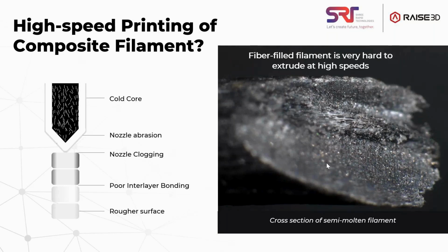So the question I get is, can you print parts using composite filament at high speeds? A straightforward answer would be no, because you could run into several challenges, or there could be limitations such as poor interlayer bonding. The nozzle might get clogged. There might be nozzle abrasion.